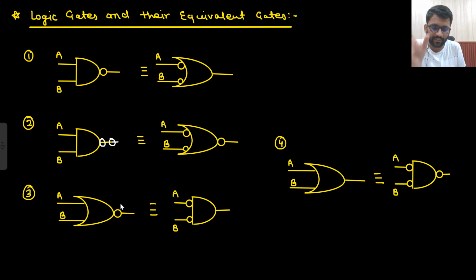Sorry, basically what I was saying, what is our AND gate? NAND gate, then another inverter. So I just replaced this gate, and then there is one inverter. So can I replace my AND gate something like this? Do you agree to my point? Basically a NAND gate and then there is an inverter.